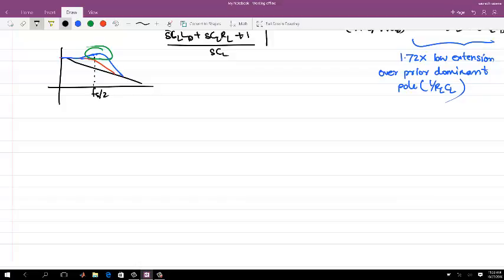If I want to increase the gain, I have to increase GM, it's GMRL, or you can say I increase RL if you are considering 1 plus GMRL by 2. If I increase RL for the DC gain, my peaking frequency comes in, 1 by RLCL. That's the dominant pole at the output. So these two things are coupled.